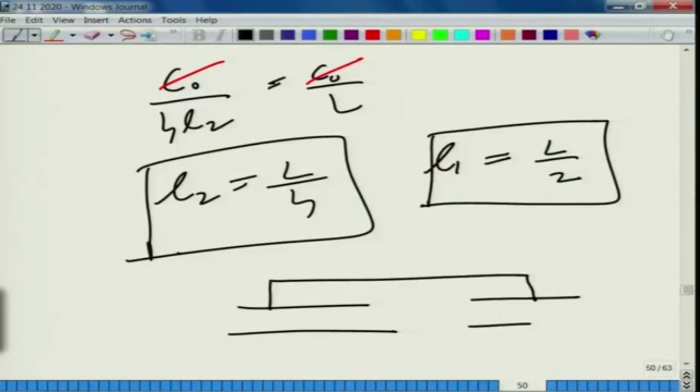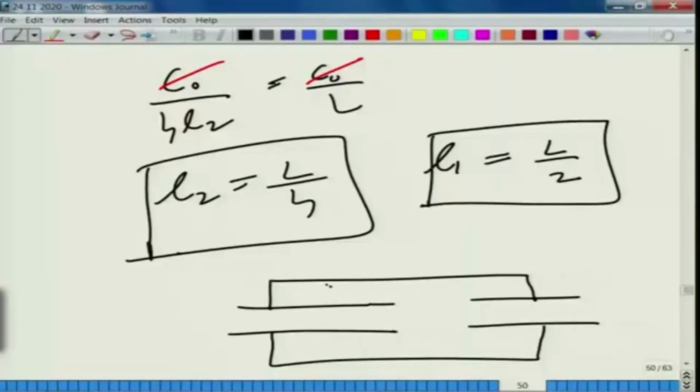Basically the idea is very simple, how to tune the performance, and we will soon see some transfer matrix derivations for this extended inlet element, and some MATLAB or Maple based simplifications in a while. If we go by the planar wave or axial plane wave propagation approach, the idea is to not just flush mount the inlet and outlet pipes, but to insert them by lengths L by 2 and L by 4.